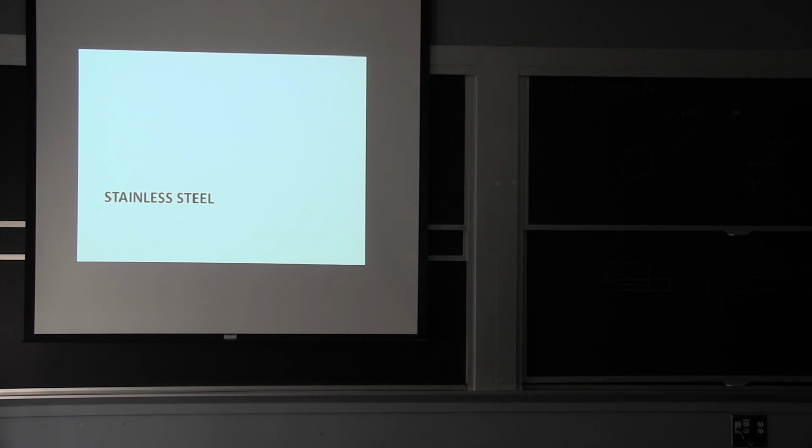What happened to it, and this was not even exactly by the sea. So the issue with stainless steel a lot of times is with chlorides. Chlorides will attack the little protective film on the surface, and then when it starts, you have that corrosion continuing. You can see a little bit of these, but this was cleaned the best way we could. And this was clean, and does it have the coating on it?